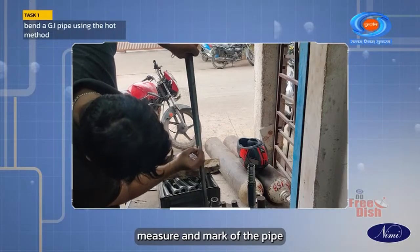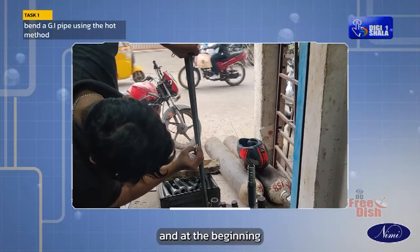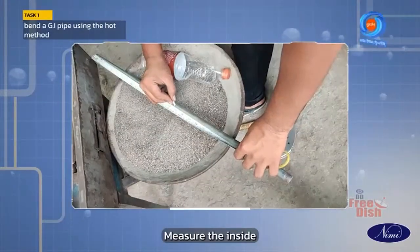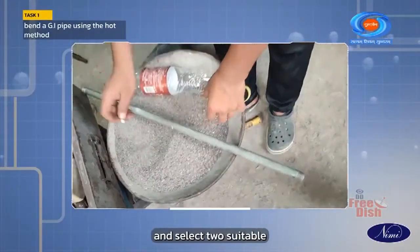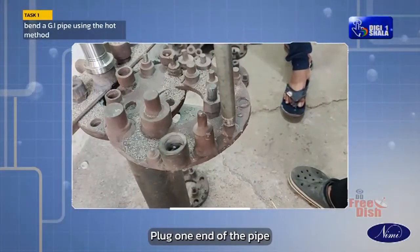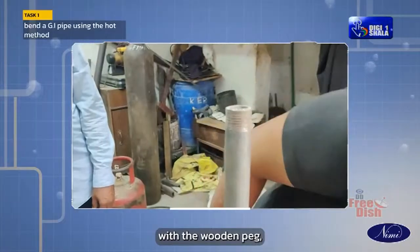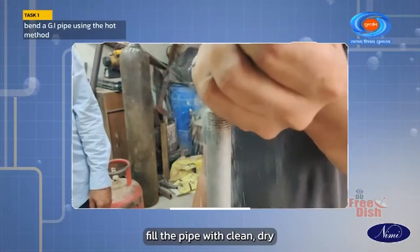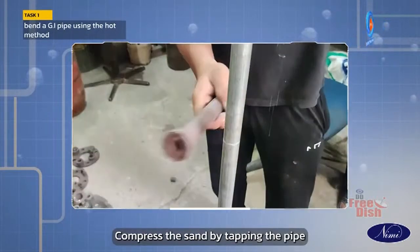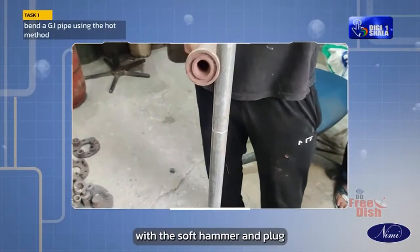Measure and mark off the pipe at the center of the bend and at the beginning and end of the bend from the center line. Measure the inside diameter of the pipe and select two suitable wooden plugs for the pipe. Plug one end of the pipe with a wooden peg. Fill the pipe with clean, dry and fine sand. Compress the sand by tapping the pipe with a soft hammer and plug the other end.